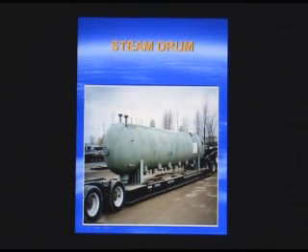Example of a steam drum. These are the downcomers on the sides. The risers are back in on the bottom center line of the heater. That's probably one of the risers here. This allows for natural circulation. This will have water in it. The water will basically flow down through the downcomer, come up through the coil by natural circulation due to the boiling off of the water and the reduction in density of the boiling stream.